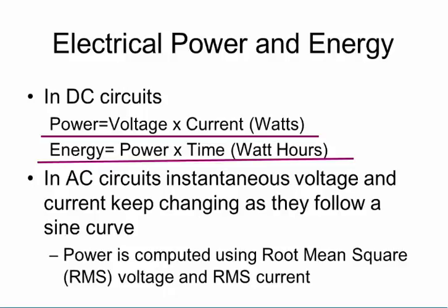Okay, there is another way to measure the waveform and convert that into a calculation value, and that is if we use what is referred to as the root mean squared. It is a value which is equivalent to a DC value of the power that goes into it.